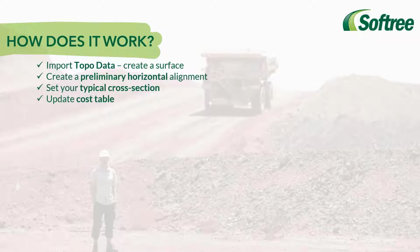Update your cost table. This has a big asterisk next to it. Even if your costs aren't perfect, as long as the relationship between the factors is reasonable, it's going to give you some really detailed results in terms of telling you which alignment is better and some improvements. So, costing with an asterisk. And then finally, adding in your constraints and variables. Constraints can be things like min-max grades, design speed, elevation control points, etc.